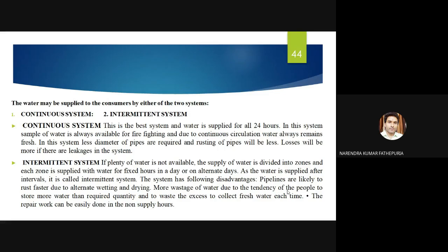In this system, a sample of water is always available for firefighting, and due to continuous circulation, water always remains in a fresh condition. In this system, smaller diameter of pipes are required, and rusting of the pipes will be less. Loss will be more if there are leakages in the system, because 24 hours water is available in the